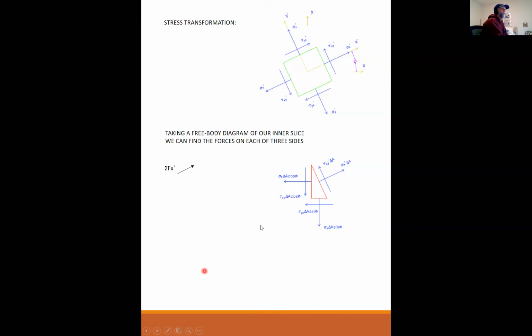So if I sum all the forces here in the x prime direction, then on this face, I have sigma x prime delta A, that's a force, minus this guy.